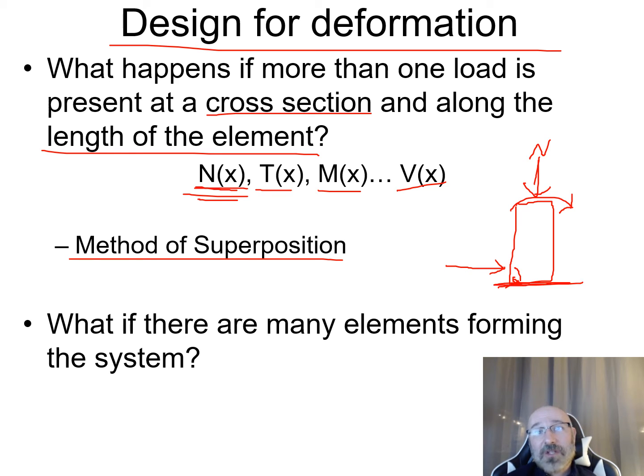So then, if this is fixed to the ground right there, is there a shear force? Or maybe somebody twists this a little bit and we're turning it as they're trying to move this in the room, and then they apply a torque. So potentially somebody just trying to move this or bumping into it, all of a sudden we have all four of these and not just this pure axial load on the top.